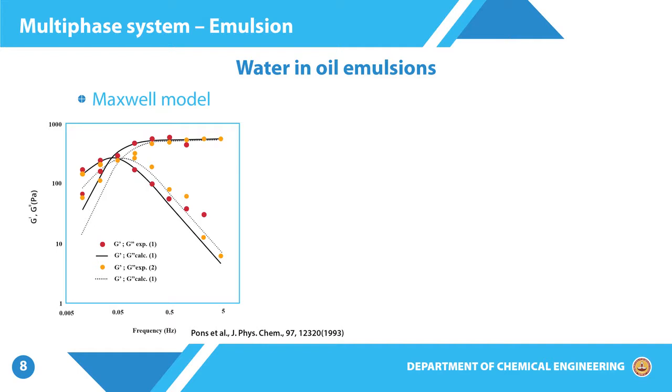of interest, and only when we do a time temperature superposition where we try to get data over significant orders of magnitude frequency or time, then we can talk about the overall set of relaxation processes which are present in the material. Sometimes it would make sense to characterize the material to such an extent, so that we get the whole relaxation time spectrum. Some other times it may not be very useful. For example, in emulsion case we are mostly looking at probing it using it as in a lower frequency range. So, therefore, this may suffice.